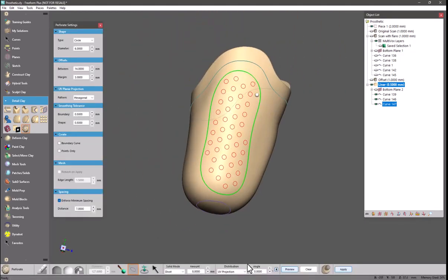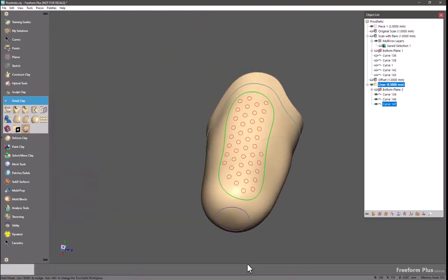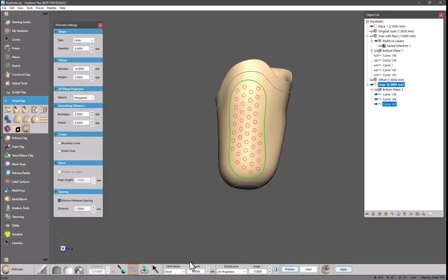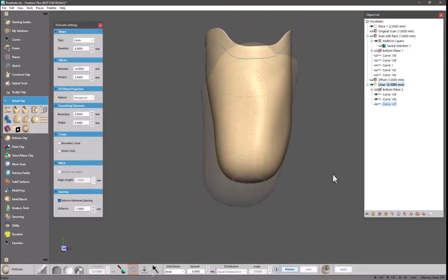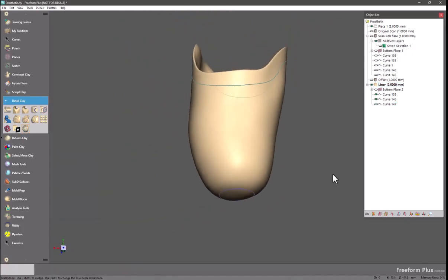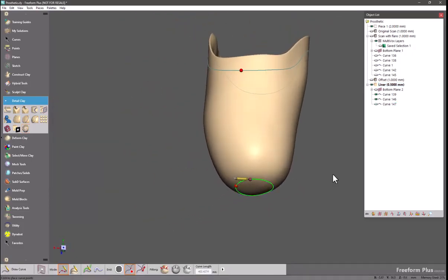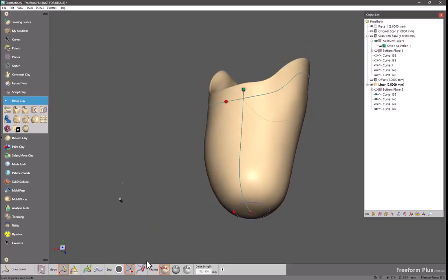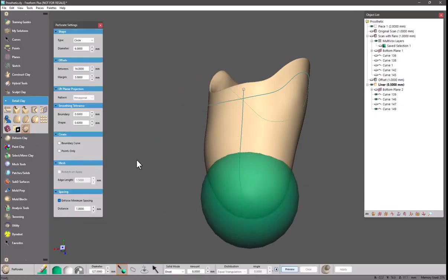And because this is a regular shape, if you were looking from one direction you could imagine this being flattened, and that is how it's achieving this type of result. You can take a model like this and create a seam. So I'm just going to do this with a fit curve. And now, because we have a seam in this, you can imagine if the cylindrical shape were cut along this line and then rolled flat, this is how it would project.